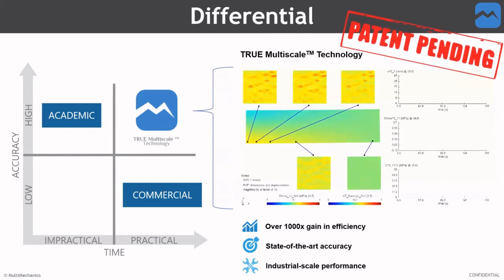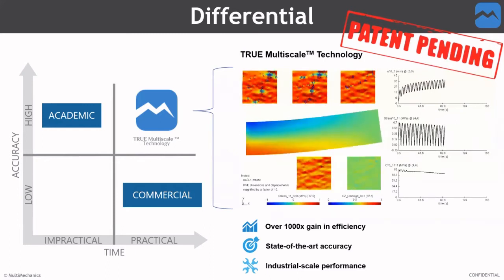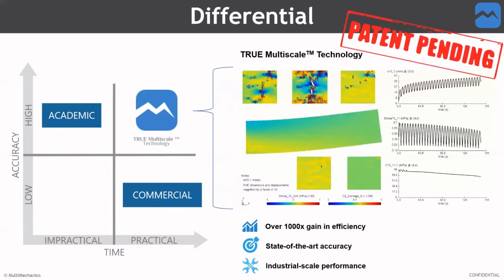The particles are linear elastic, and the matrix is a linear viscoelastic material, and a cyclic load is applied to the beam. We can clearly see microcracks initiating and propagating along the load cycles. And each microstructure evolves differently depending on the loading history they experience.